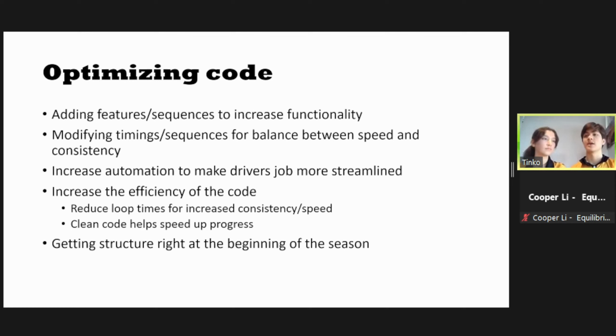And then also obviously a large part of optimizing your robot performance and speed especially, and consistency, is modifying the timings or the sensor inputs. So you have a sensor to change states for a specific sequence, modifying that, and then tuning what actions come after one another at what times. That's a great way, really through trial and error, that you can get better.